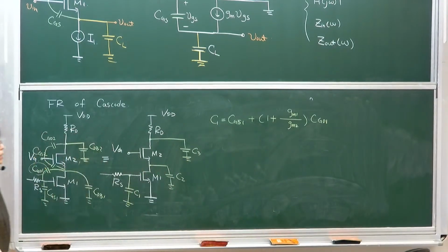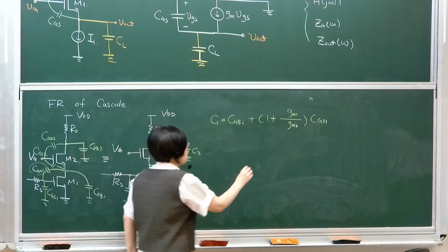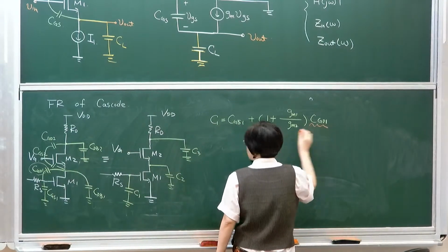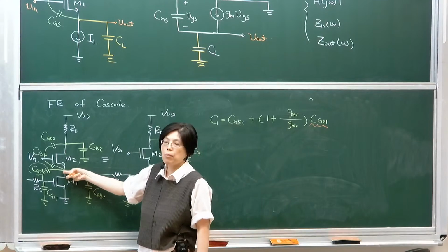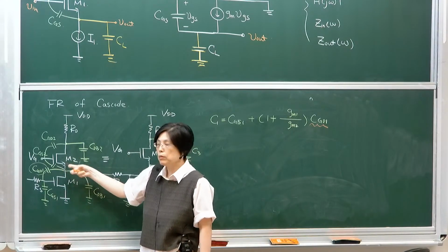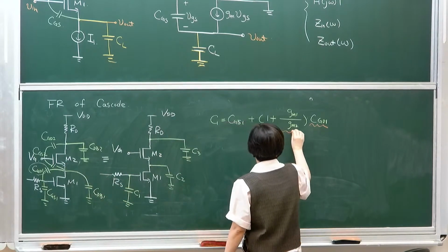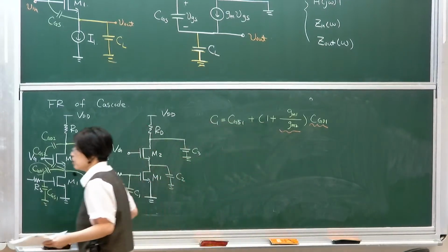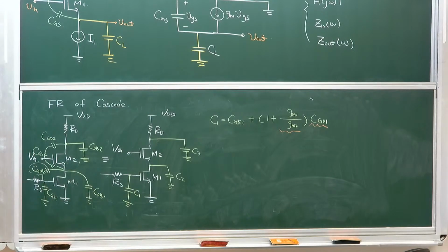Even though at the input terminal this is being amplified, this node does not amplify too much because of the low impedance at the source terminal, so the amplification is typically close to 1, and you only see twice the level.